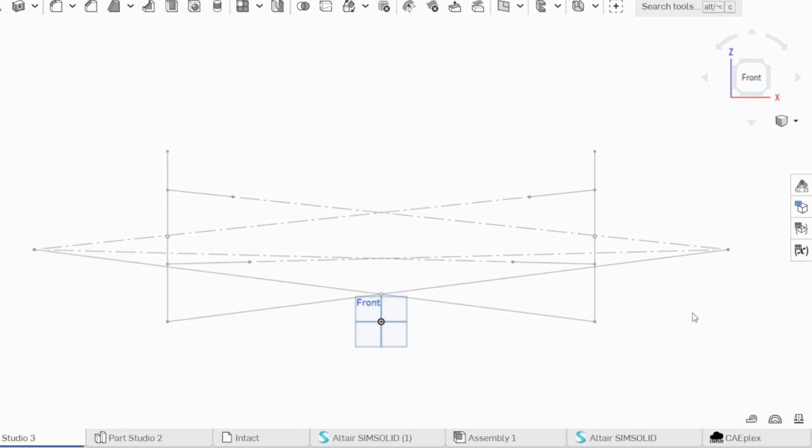So why would you use jacking force? We're using the roll center to calculate weight transfer. You'll get weight transfer of how much your left and right, front and rear load on your tires is changing, which is good. You can use that to tune your car. Just know that it is a simplification, and it won't necessarily be exact, but you'll get the change, if that makes sense.